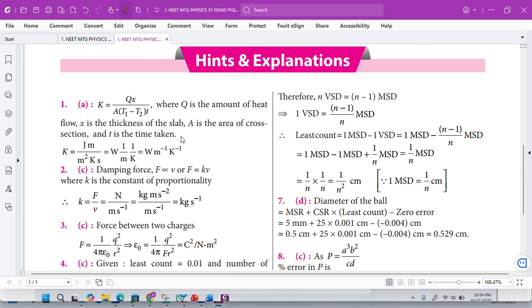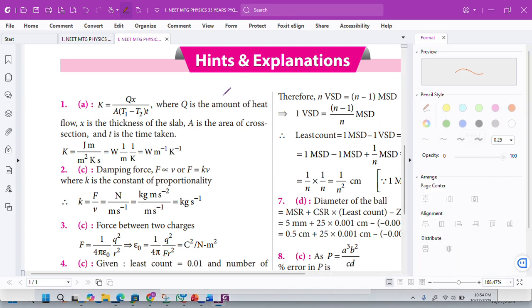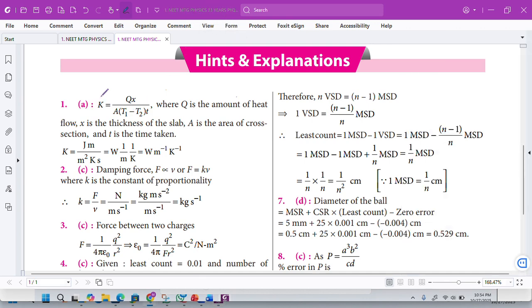Now we know that to solve this we need to calculate the thermal conductivity unit. How can we see that now? I can solve this numerical with the help of Fourier's law of conduction equation. What is that? Q is equal to minus K A into dT by dx. This is the equation, dear students.